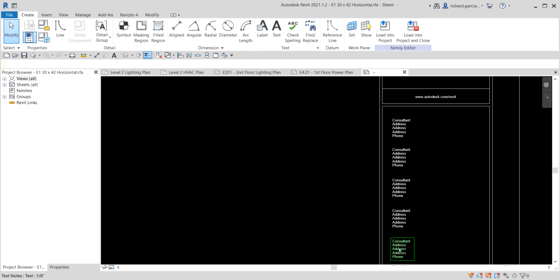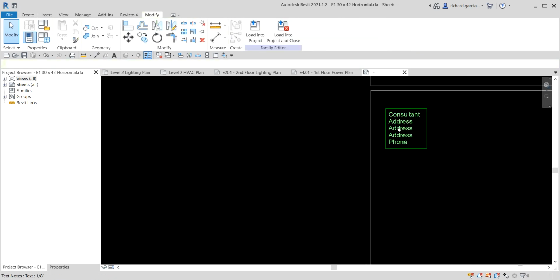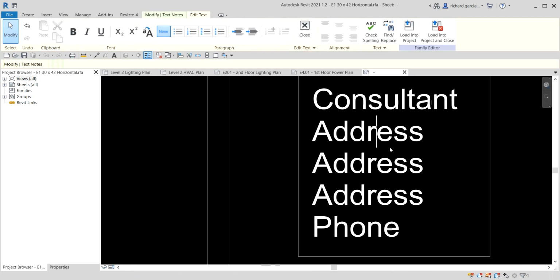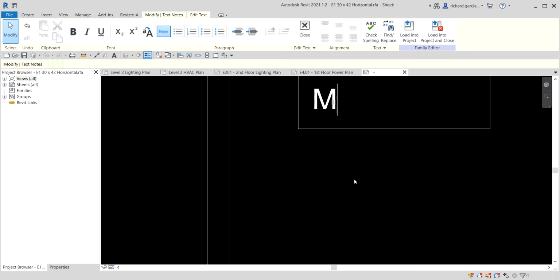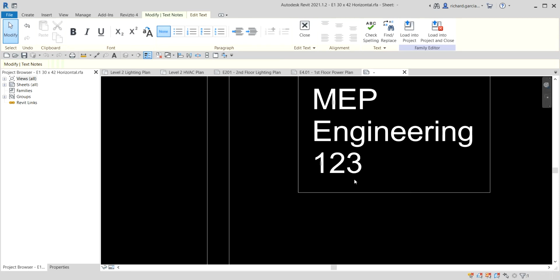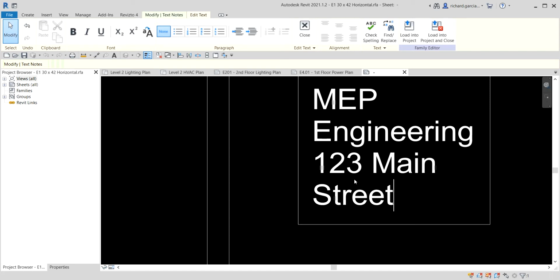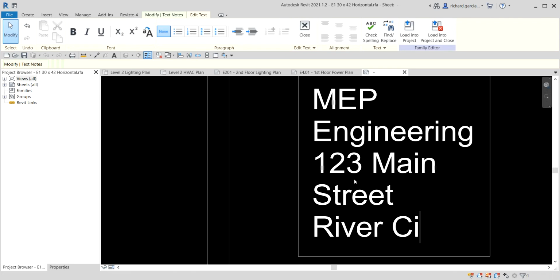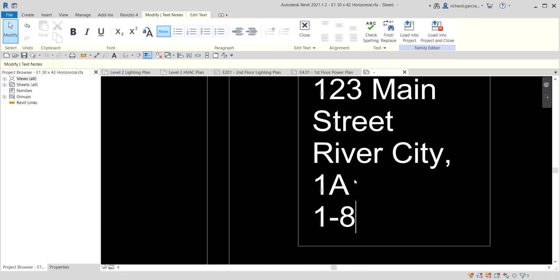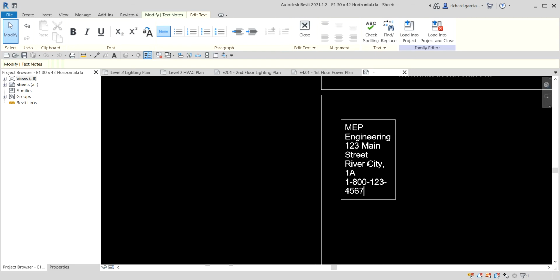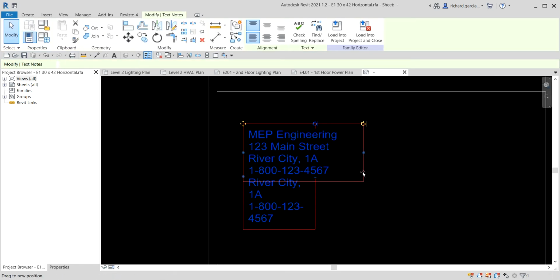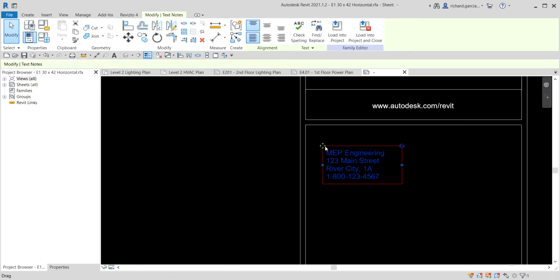So let's say I'm going to delete these things here and then I'm going to put here, let's say, the address or the property. Let's say I'm going to put here MEP engineering, enter. So let's say 123 Main Street, enter. River City 1A, enter, and then let's say the telephone number 1-800-1234567, something like that. Then just click outside, and then we can resize this one. There you go. So let's say that's the information that I want to be included in my title block.